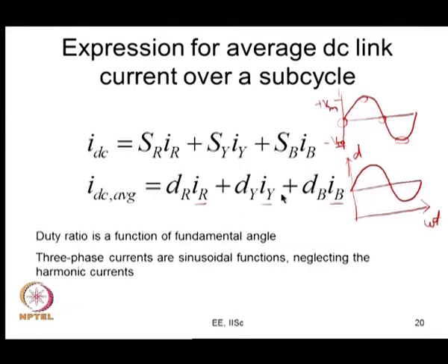The same thing, this will also give a DC. In fact, they are all symmetric, so it will be the same DC. So, you will also have a DC now, and the DC components will all get added up. The question is about the AC component. In the case of a single phase rectifier, you will see that there is a 100 hertz ripple. Here, what you would actually expect is a 300 hertz ripple, but the 300 hertz ripple would theoretically come out to be 0, or it will turn out to be very small.